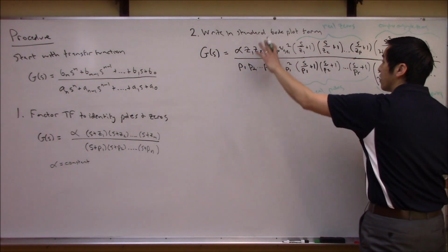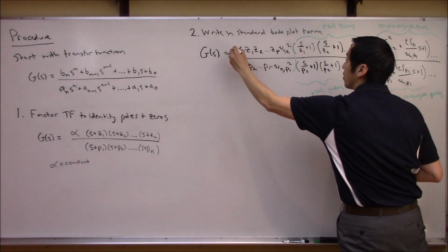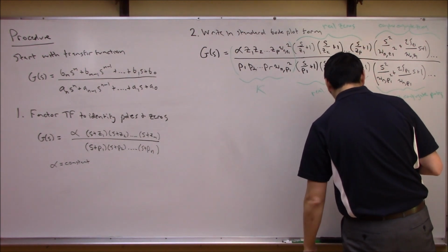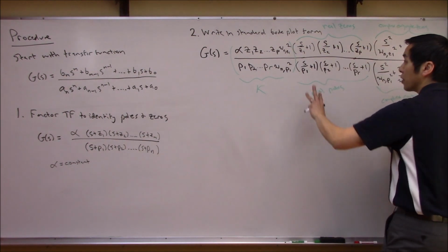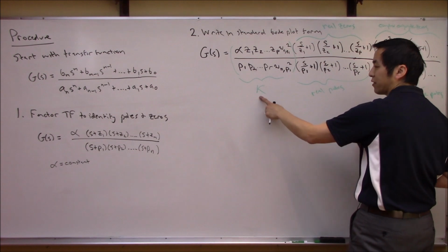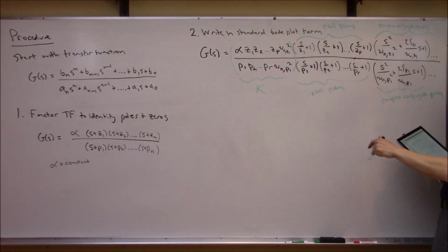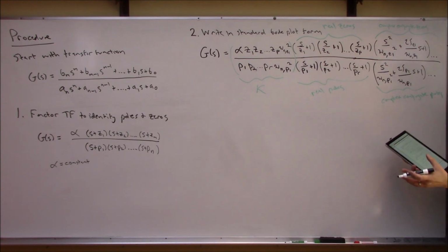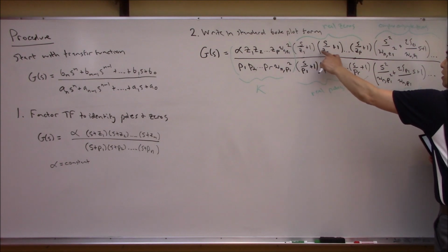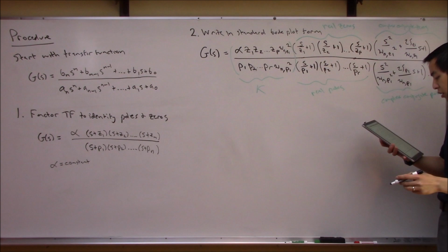So you could generalize this, but what I'm trying to get at is, if you look at this entire gobbledygook over here, all of these constants, this whole thing becomes this constant gain K, your offset. So really, you write your transfer function as some ugly mess of constants, and then everything over here is all written in the nice exact format that we explored last lecture. We now know how all of these zeros contribute, how all of these poles contribute, and how this constant offset contributes.